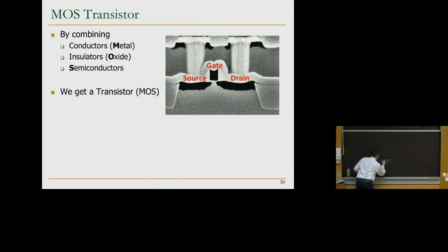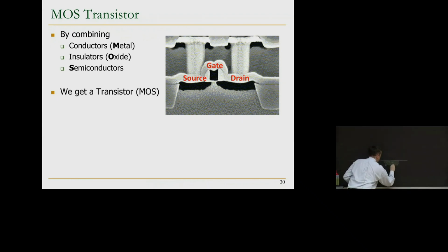And this region here is going to have this stronger doping. So this is a semiconductor, and this is a part that we engineered. We start with a slightly, let's say, P region, and inside it we manufacture, and we say here we are putting some impurities, and we create these regions, these two parts. Then we cover, between them, we cover this part here with an oxide. We don't want any current flowing through here. So this is the oxide.